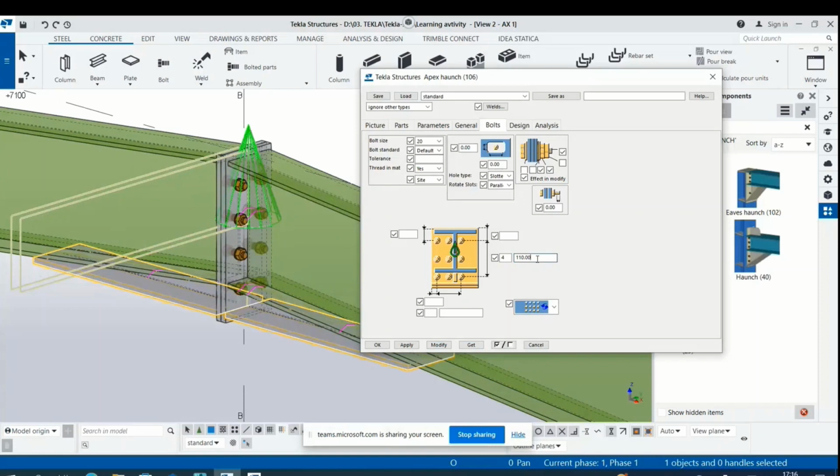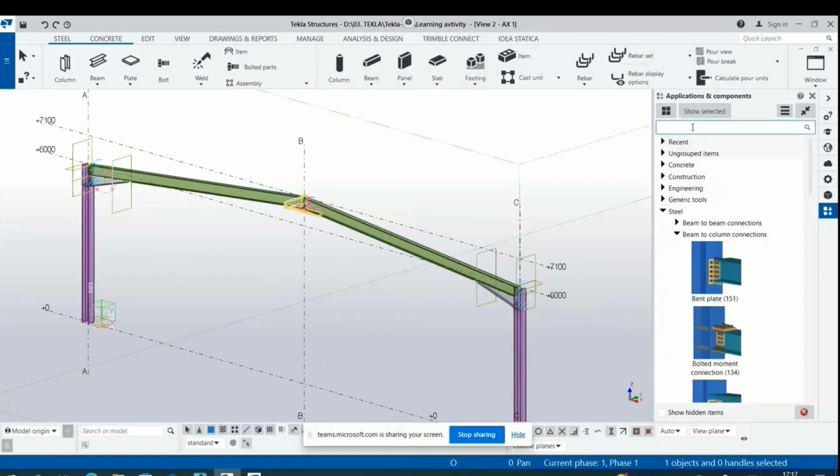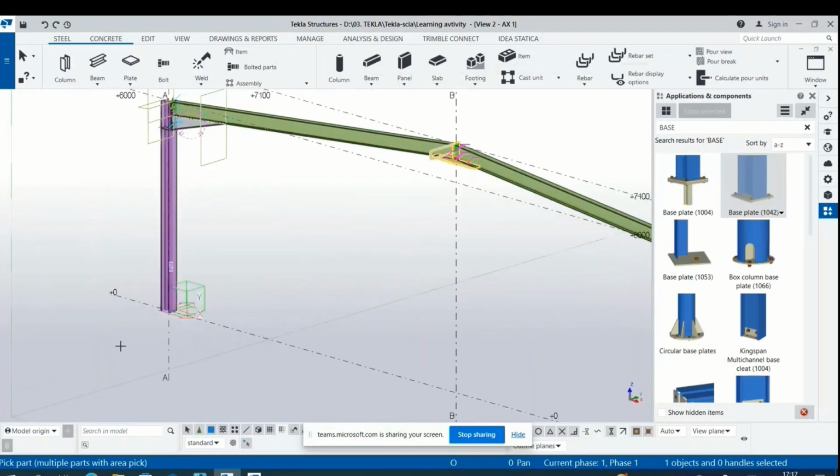It's not necessary to use a rigid connection, because for a rigid connection it's necessary to have a lot of bolts, and this means material, this means manpower, and this means money. It is not necessary. If seismic codes ask for this and you cannot use a semi-rigid connection, it's necessary to make a rigid connection, and we will do it.